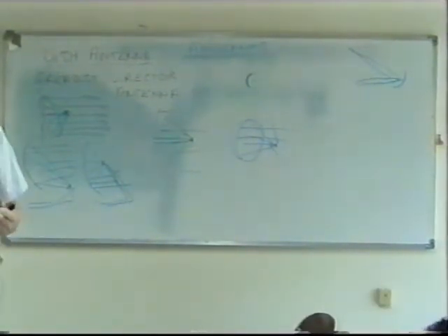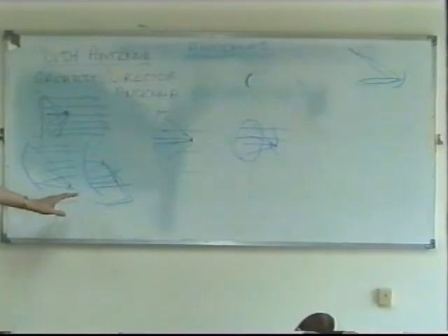Small dish we have seen. Yes. Well, the size of the dish, that's something I haven't mentioned too much about yet. What do you think that depends on? Yes, it does depend on frequency, wavelength, that's right. The higher the frequency, the shorter the wavelength, we can use smaller dishes.